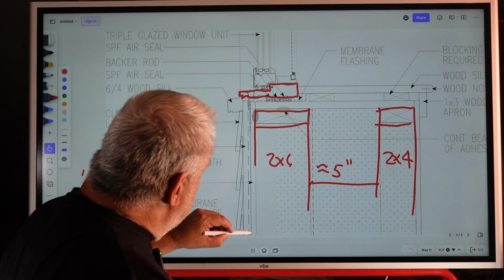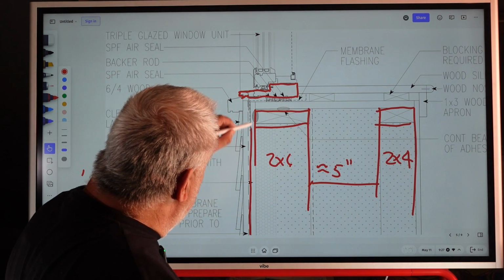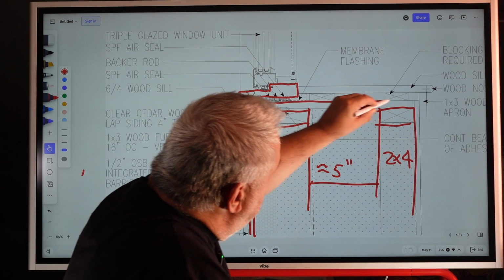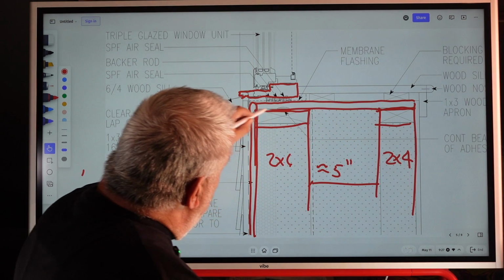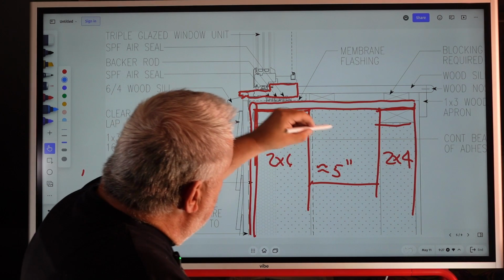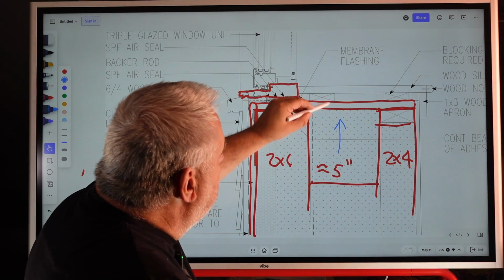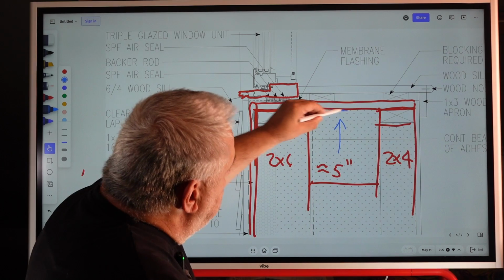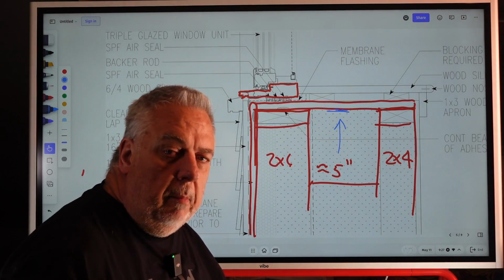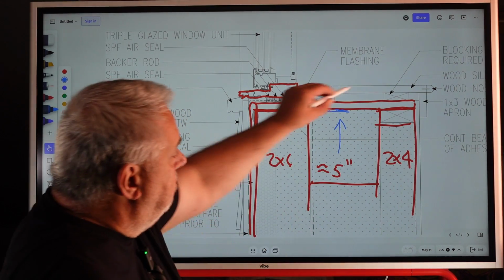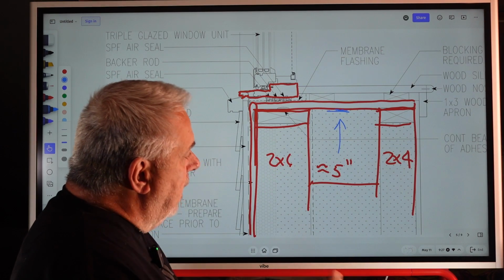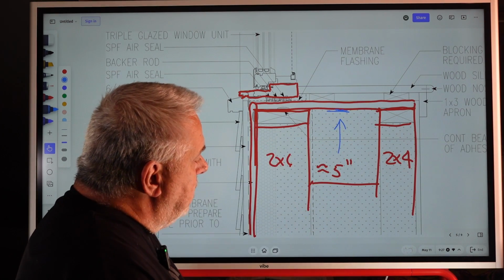But also notice that our sheathing here came all the way up, and our sheathing went all the way back, right? And we needed to do that because if we had fire coming up through here, we needed to be able to stop it on that double wall construction. So you have to compartmentalize it. Not that the sill or that wouldn't do it, but if you have it come up, then it gets in all these other channels and the fire can spread. So we just closed it off.